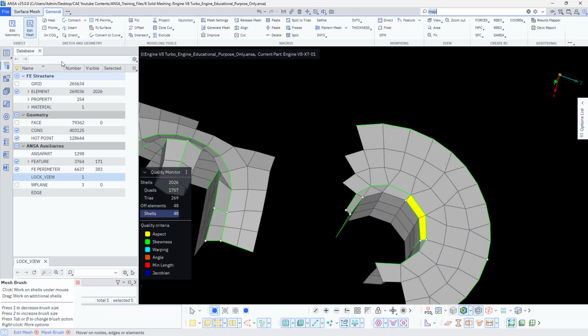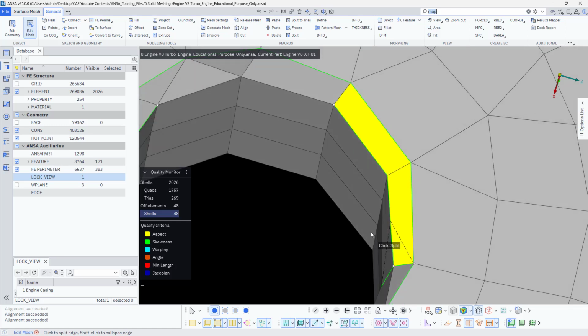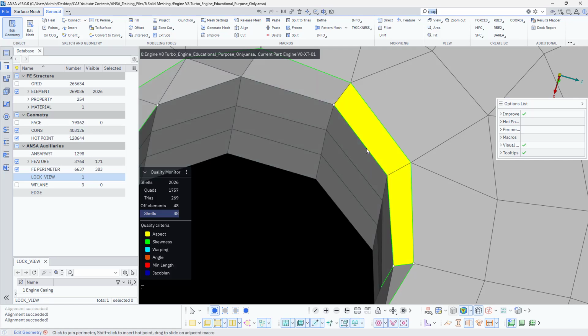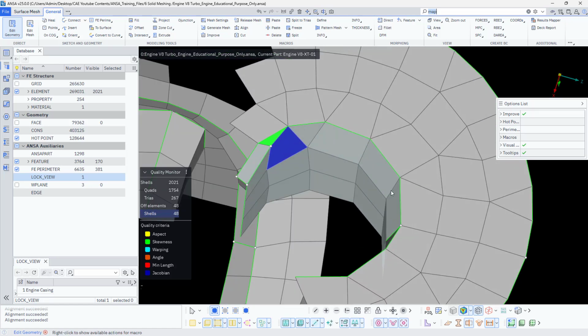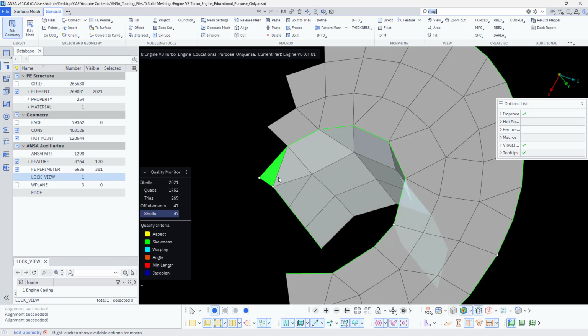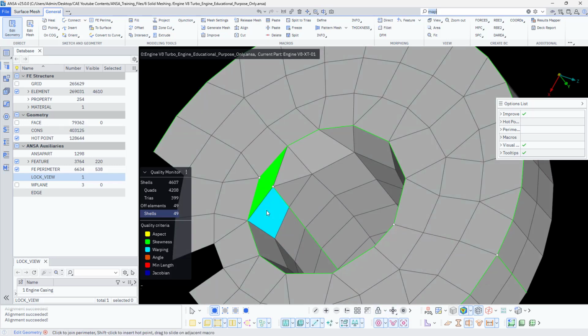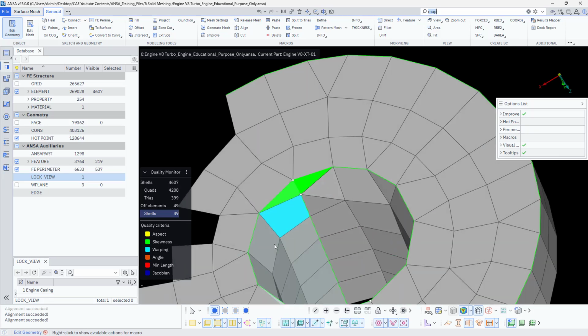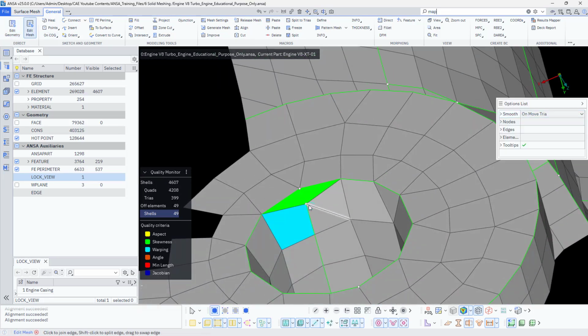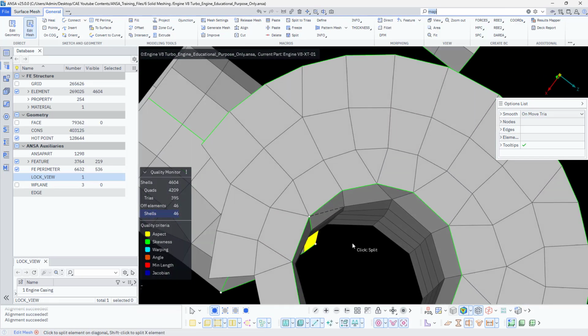Right? So I can switch to direct mesh, or else you better remove this perimeter. So that would be great. So just check whether improve is activated. Just remove this so that it will be automatically connected to that row. So here also you do the same. So if I take one more layer, so we have this continuous hole. So if I remove this, here I can just manually join this. Yeah, like this.